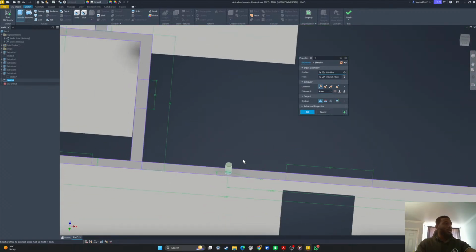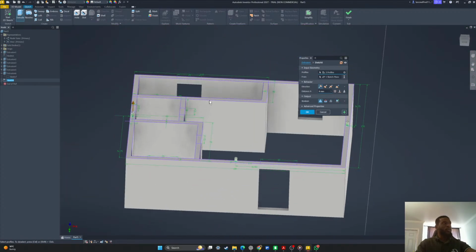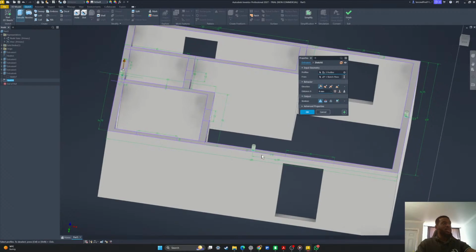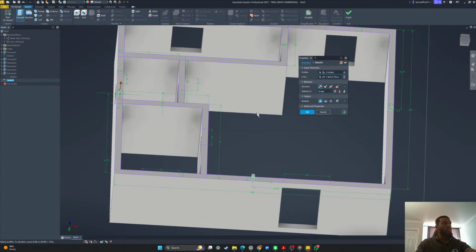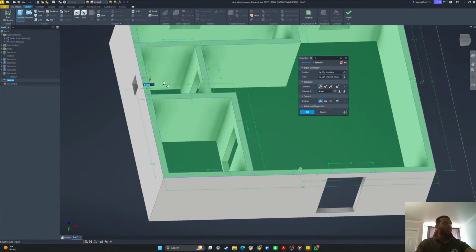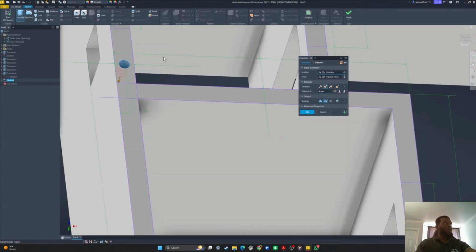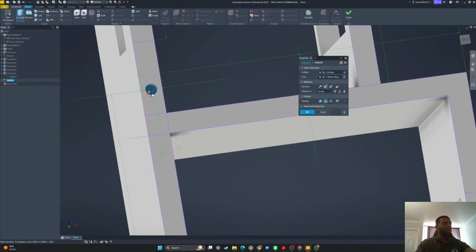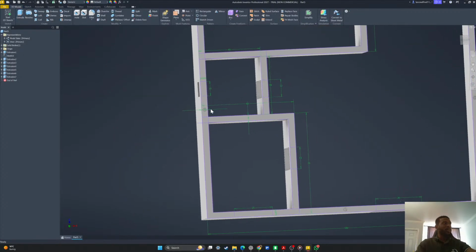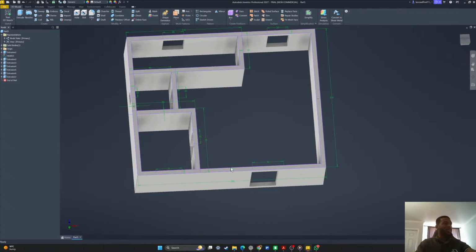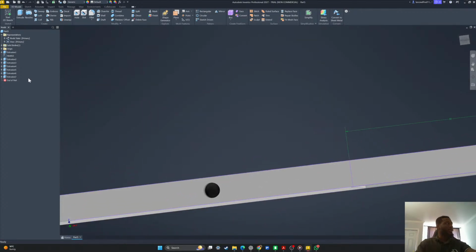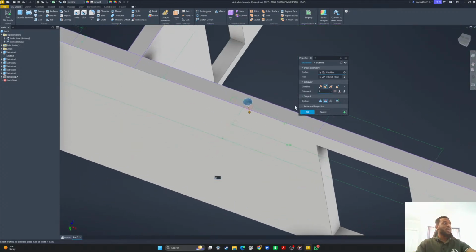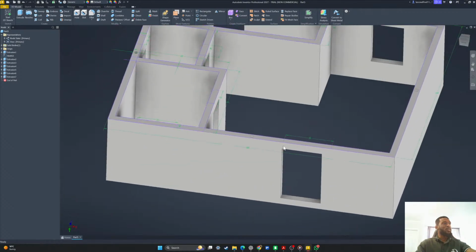So now if I was going to make the holes on the roof of the building, I would leave this way. So the building is going to slot into the roof, but I want the roof to slot into the building. So instead of making the slots, I'm going to make holes instead. So the roof is going to be the part that has the slot, and it's going to go in just like that. And we have it right there. Same right there. I made it 2 mm deep, so we don't want it to go in too deep.